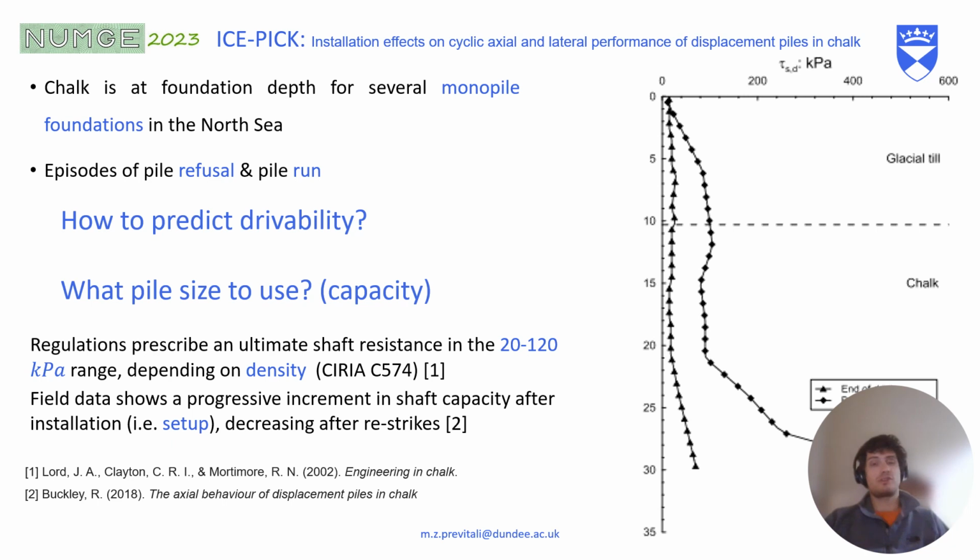Additionally, for the capacity, field data shows that a progressive increment in shaft capacity is achieved after installation, or setup, which then decreases as the pile is loaded again.